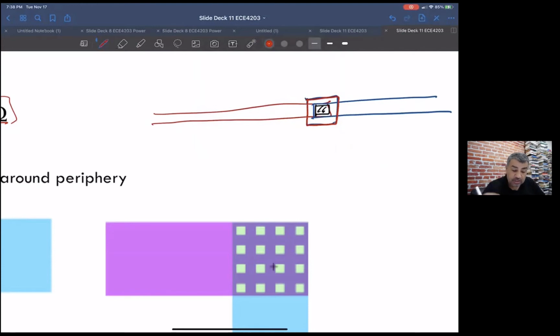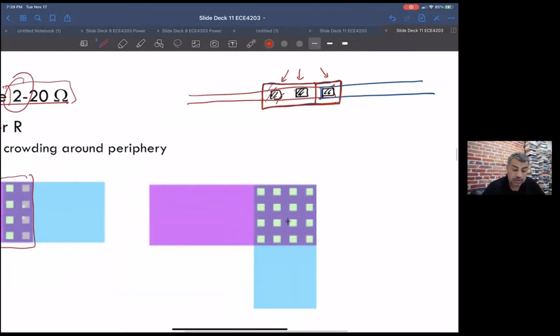So if you have the space, the thing to do is to drop in multiple contacts and extend your metal 1 to cover. Again, you can take this as far as you like, but get as much overlap here. And now you've got 3 vias in parallel, so you have a third the resistance, and it can be pretty significant.